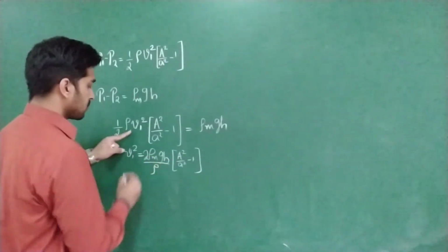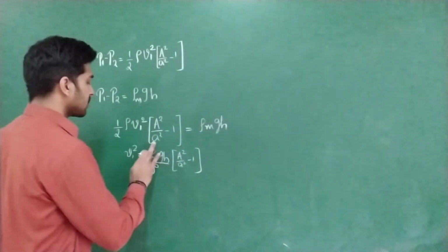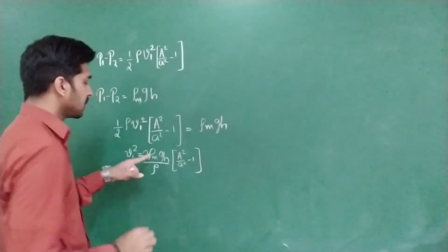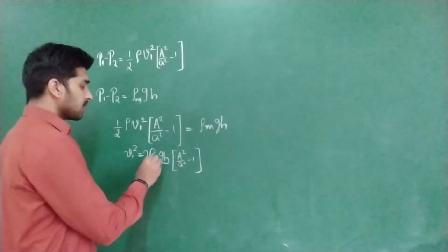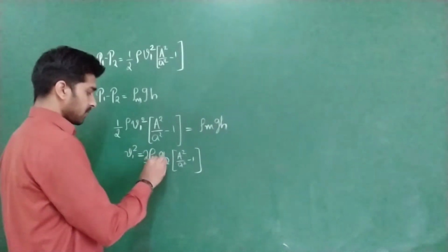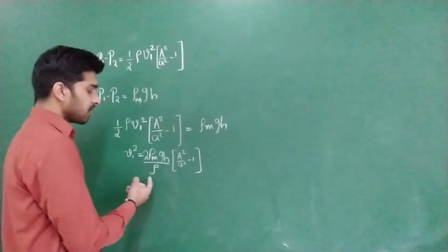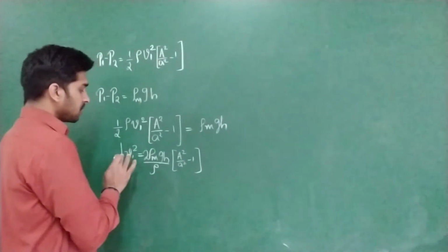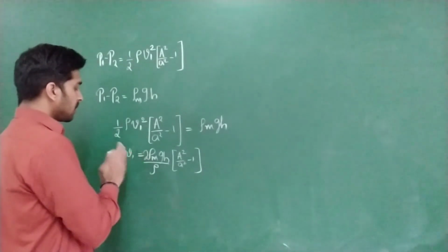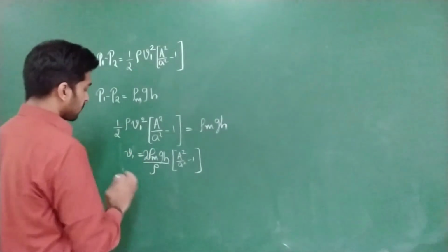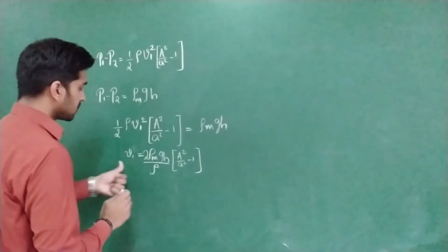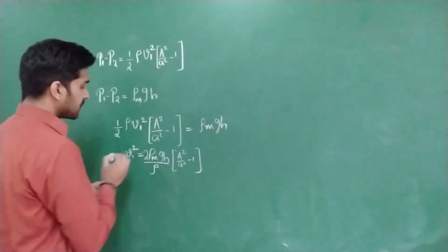by this rho. Okay, this rho and rho you should not cancel, because this rho is nothing but what? Density in that U-shaped tube, and this density is nothing but what? Density of fluid which is passing through what? Venturimeter. Okay, and next here we got actually V1 square.